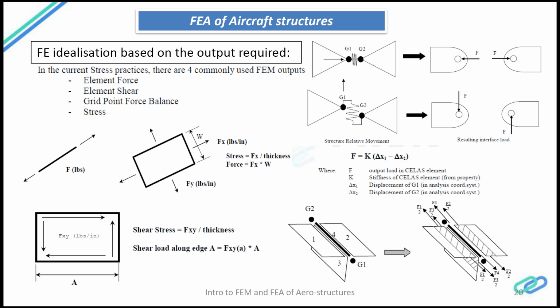When you take a cut section in the middle of a beam, you get the free body loads. So similarly, there are free body elemental loads that are being shown here. How it is being calculated, you can see the force from the rod elements and also the force from each of those flange elements and forces from the web elements. The total force on one side is the total force divided by 2.